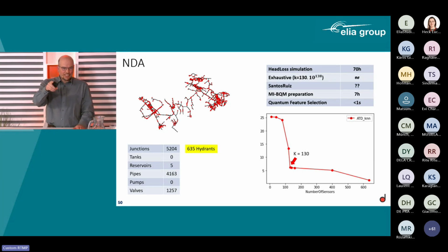And then you see that curve again, it drops off towards 130 sensors spread over, and you see also the extremities coming back. So that was good. And then it levels off. So here the answer was, if you take 40 sensors, if you do that investment, you could as well put one. Or you really have to go to 130 to do better as a measurability of your topology, basically. So that was very interesting for them to know. 40, they didn't have a guideline, but it would be better to triple that investment anyway.